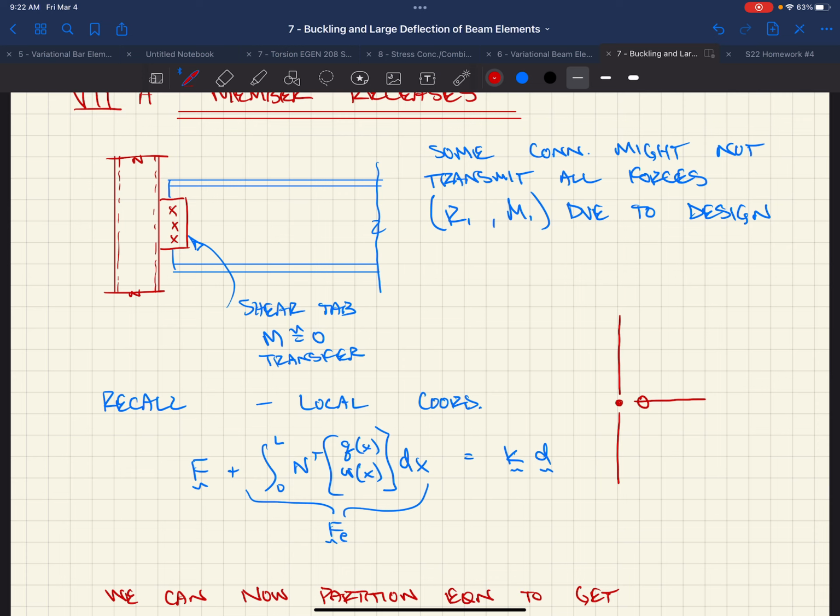Yes. So that connection in that shear tab, it's made to allow rotation by yielding, they want it to yield. Yeah, so the way you design it, you make it thin enough so that there's flexibility there, so that you don't get fixity. You just count on extremely minor rotations. Yeah, I mean, you're talking at ultimate loads, right?